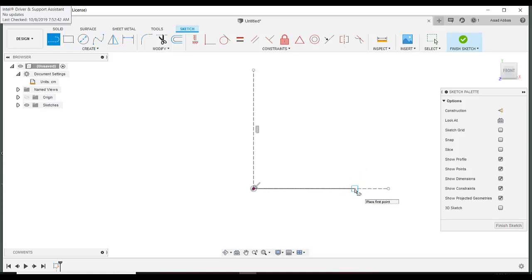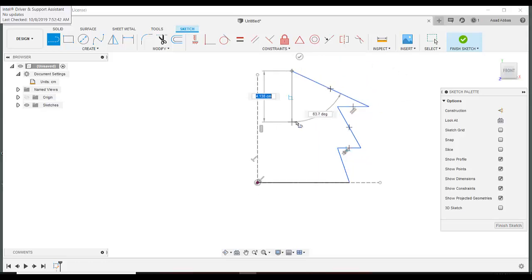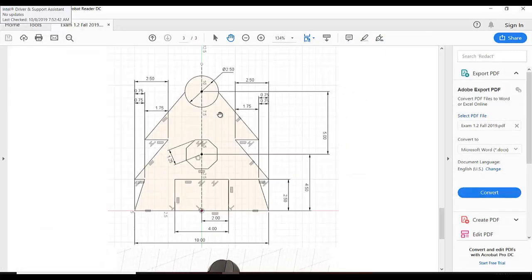So again, start a line from here, draw a line like that, then go here, draw a continuous line, and then go here. The automatic relations are going to be added, then go here, just draw and end your line like that. If you go to the sketch, I just drew a random line. I did not edit these dimensions. I just drew the rough sketch from this point.